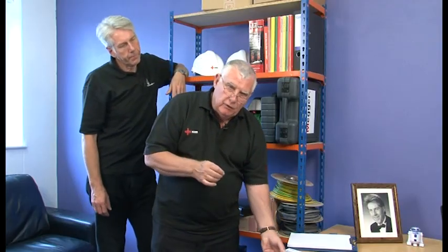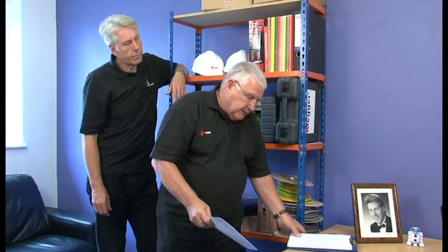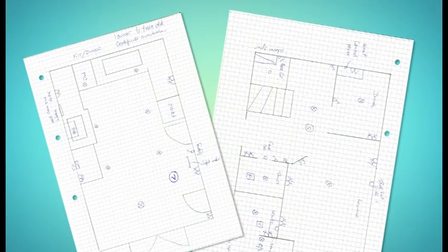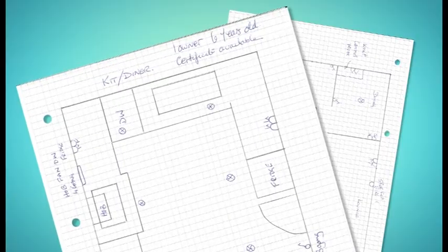So with regard to recording the results, what do you recommend, Tony? Well, I'm going to be taking along a colour photocopy of the NICEIC Domestic Electrical Installation Condition Report form. I'm going to be taking a sketch pad for me to do a few layout drawings, making a note of the number of points, readings and of course any comments that I have. Although not a requirement of the regs, having a layout drawing of the installation speeds up the process and can be a handy reference source for the inspector and also the client.